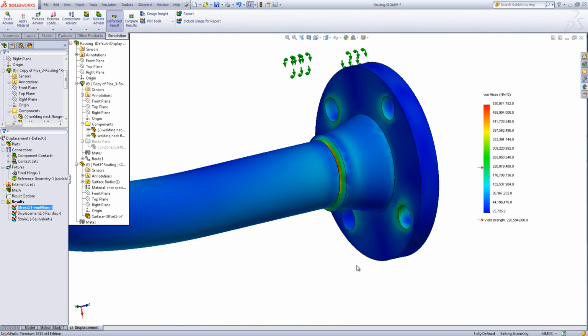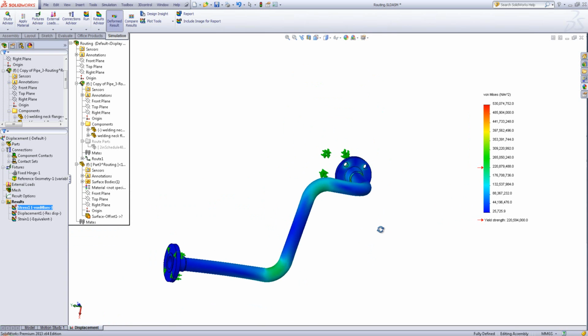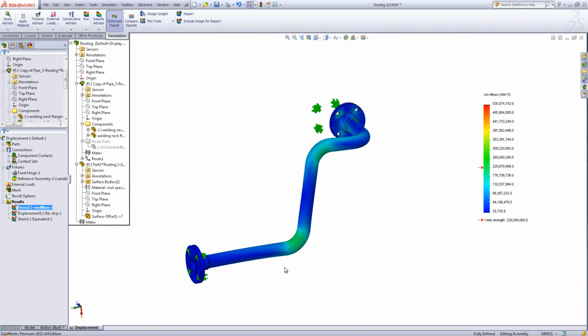Finite element analysis doesn't really like contacts like that, because what we're doing in this case is bonding 2 bodies together just by an infinitely thin edge. Because we've got elements on that infinitely thin edge that can't move or have to move relative to the pipe, and we've got elements that are immediately adjacent to those that can move somewhat freely, we do get large spikes in the stress values, and these are what are referred to as singularities. So we would negate these. In actual fact, I'm going to show you how to concentrate on just the pipe in a moment.